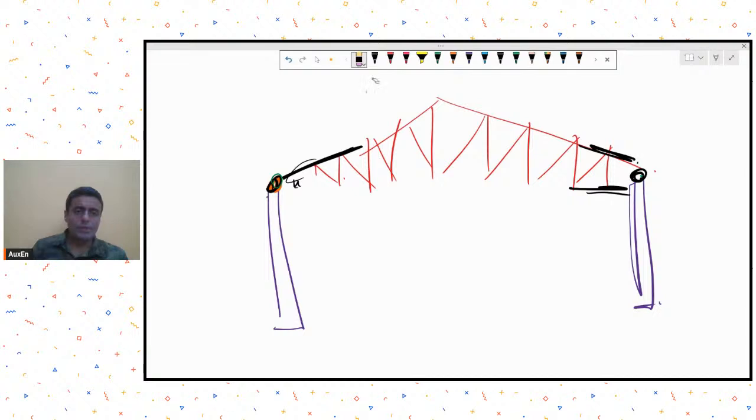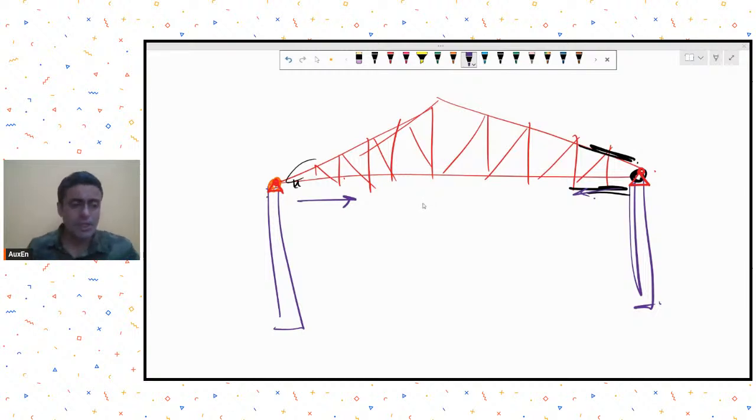So then what people do is that they say I will have a hinge support over here. Hinge means that it is not able to resist any moment. It allows full rotation. Now the problem with having a hinge on both sides is that there will be a high amount of thrust created, and that horizontal thrust is to be taken by your chords, and then you will start seeing problems in your chords. So a hinge on both sides is also not a great option.